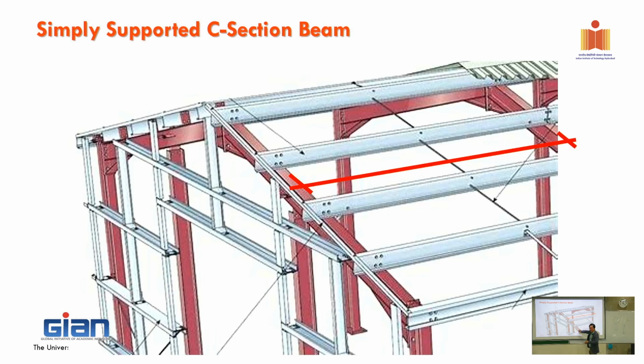So when the wind blows into this one, it actually blows the roof off. So it means that our bottom flange here, there's nothing to hold that. It's just this rod in here. So then you can check for flexural torsional buckling. Otherwise, if it's going down as wind or snow or whatever, you have the roof sitting on top. There's no problem with flexural torsional buckling, right? It holds that beam from flexural torsional buckling, okay? But now if you go uplift, there's a problem because you have nothing to hold the bottom flange, and the bottom flange in compression is very, very sensitive to buckling, okay?